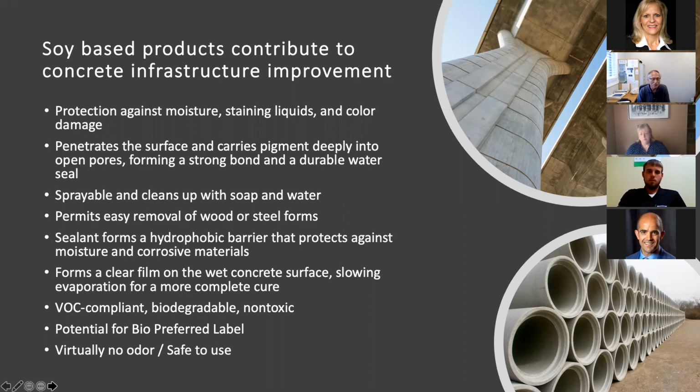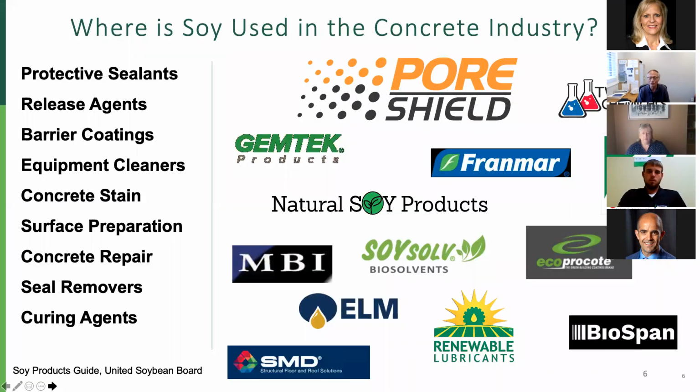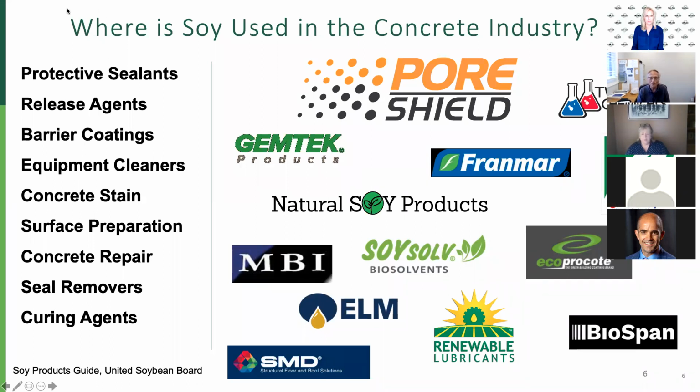It is a VOC compliant, biodegradable, non-toxic material. Products are listed for a Bio Preferred label. And like I say, it's a good product to use, low odor and good safety in using it in concrete products. So some places where it's used: protective seals, release agents, barrier coatings, cleaners. It's used in the stain, surface preparation. It's also used in concrete repair, steel removers, and curing agents. And here's some examples of companies that utilize soy products in their concrete industry products. It's a good story.